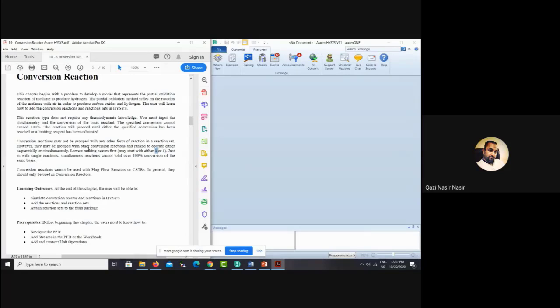You don't understand these things right now, but when you start, then you will understand. But ranking is very important. If you have multiple reactions, you need to tell Aspen Hysys which reaction is happening more and which is happening less. If you put 0, Aspen Hysys considers that direction is happening less. If you put 1, then Aspen Hysys will know that this direction is happening more as compared to the second direction.